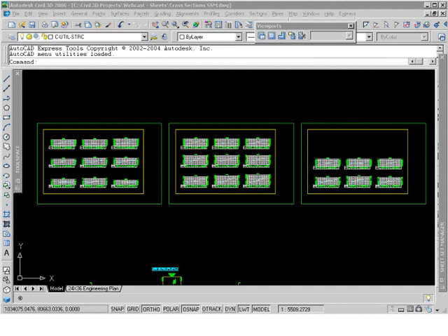So as I said, we're going to be looking through two different methods. What I'd like to first start with is something that ships with every Civil 3D, is the fact that we're built on AutoCAD and AutoCAD 2006, and we're going to utilize the Sheet Set Manager in AutoCAD 2006 and go through some of the things we can do to set up the Sheet Set Manager and get that to work for us in a civil environment. And be able to have it automatically, or not so much automatically, but ease the creation of our sheets.